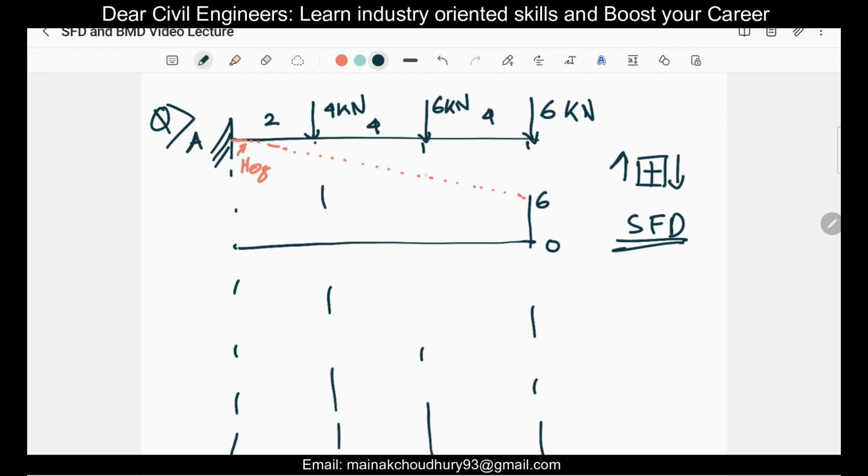Then there is no force up to this much, so we'll have 6 up to here as well. Here another force is coming downwards, and downwards is positive as per this sign convention. It will add to this 6, so it will be 6 plus 6, 12. Then it will go up to this much, and again a downward force is coming, so it will be 12 plus 4, 16. This is the shear force diagram, very simple.